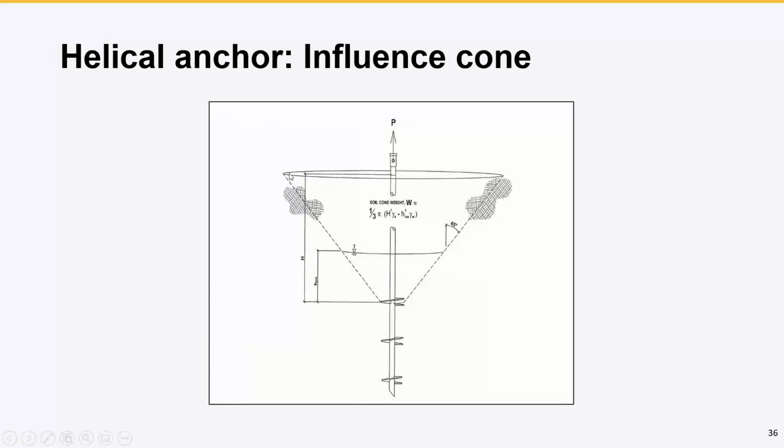Basically, he calculated the weight of this cone of soil and equated it to the pull-out pressure using the individual bearing plate method, and he came up with the minimum embedment depth. The minimum embedment depth he came up with is really very close to what they got, and that's just using 45 degrees.